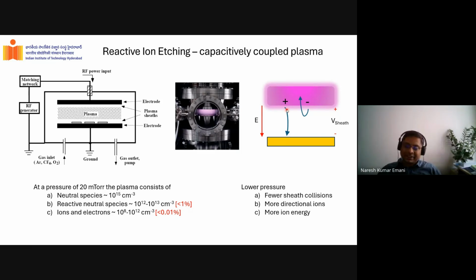But anyway, in essence, what's happening is, if you're very close to the surface, when you have this ionization happening, when your RF source is switching, these electrons do not need to travel far. They are very light. They will travel very quickly, right? So what ends up happening is, in the small region, you don't have any more electrons here. They are completely taken out of the substrate. And so because of that, there is a positive charge that is slightly far away. And this region where there is essentially no plasma, close to the surface.